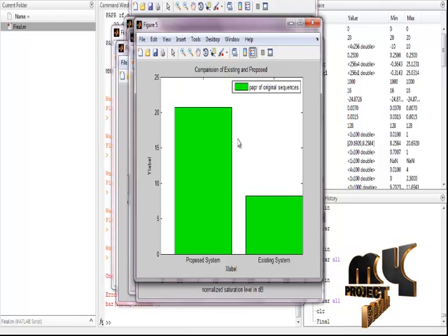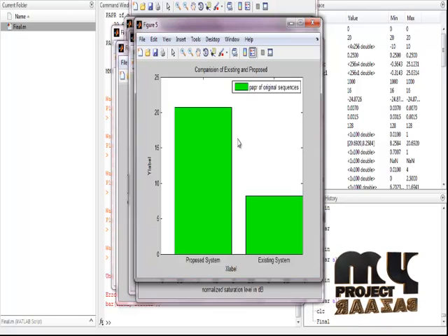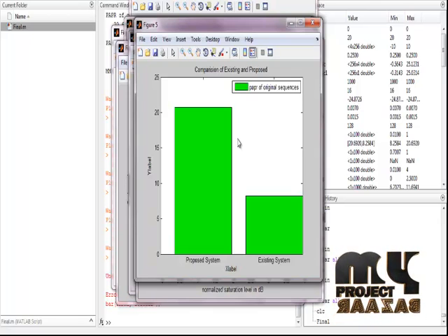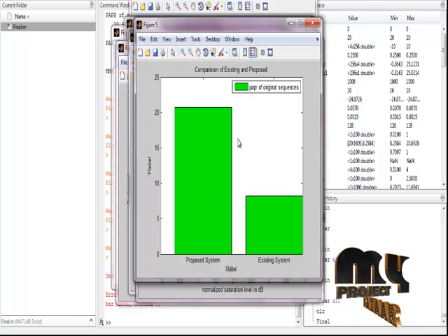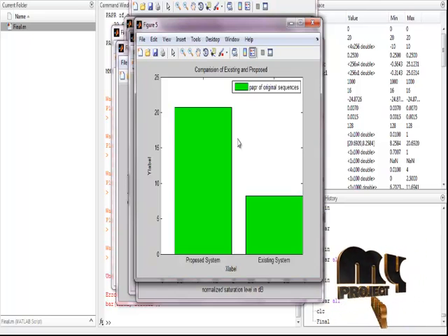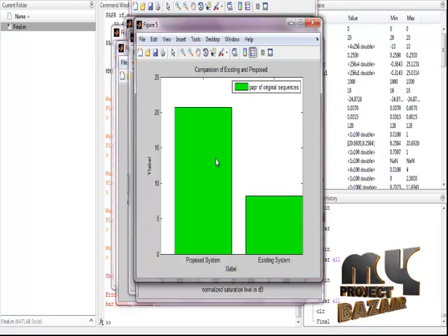Now we have to conclude the process. In this process, we use the signal cancellation method, a suboptimal signal cancellation method, to extend the cancellation points dynamically, and then add the signal cancellation symbols to the users for joint PAPR reduction and to suppress the sidelobe of the original sequence very effectively.